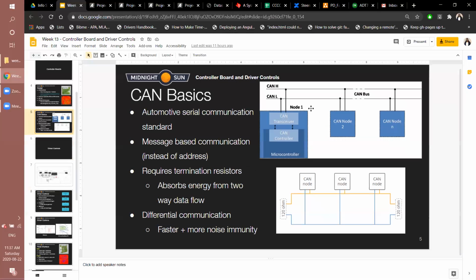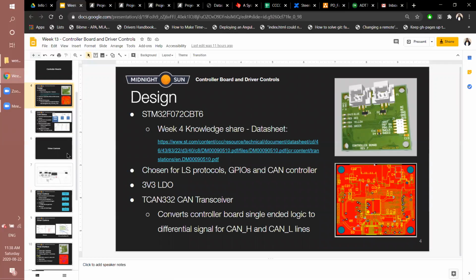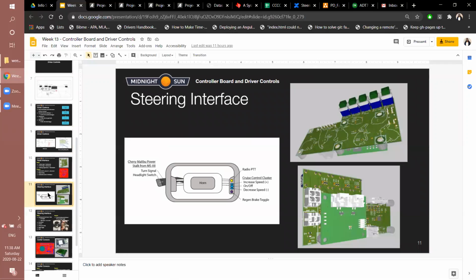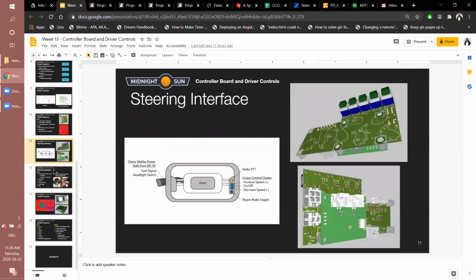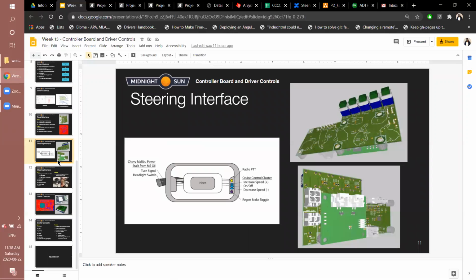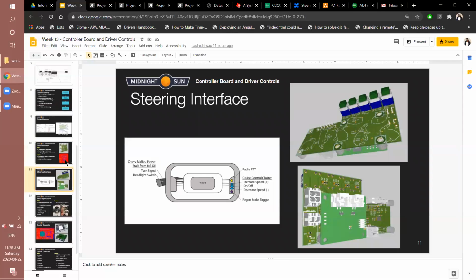Cool. Just an additional thing, the filtration is really a big part of these boards. And we've tested it. One of the first things I worked on actually was the noise on our previous versions of all these boards. We didn't have filters. So if you communicate with a walkie-talkie near any of the boards and then scope the values you're seeing that would be entering the controller board, you could see huge ripples on the analog and digital lines.